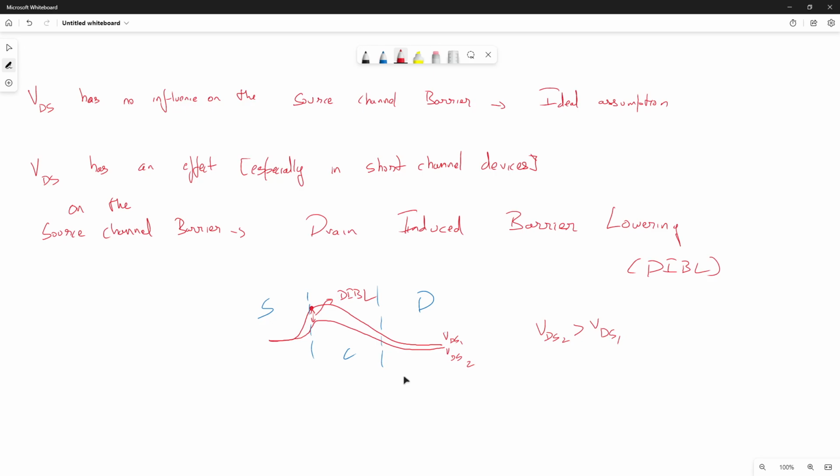So it will kind of drag my current down. Of course, more charges are available, but because this barrier height is low, my drain is no longer able to drain the electrons efficiently. It is actually reducing the charge accumulation capacity of my channel, and it is affecting the transport properties. So my current will slide lower in spite of the fact that this barrier is falling.